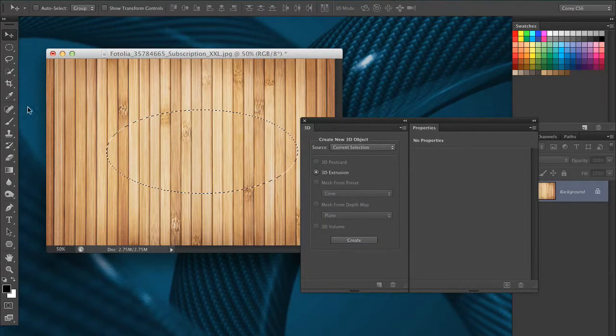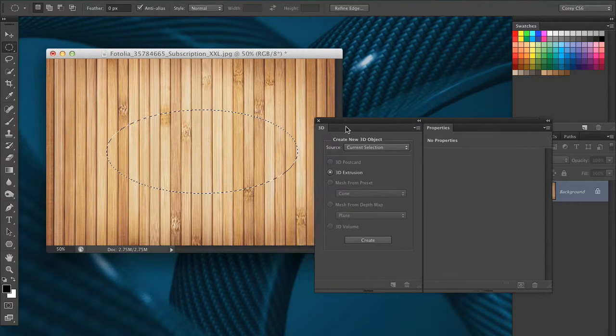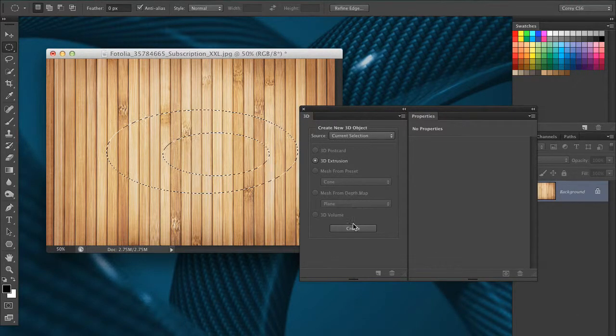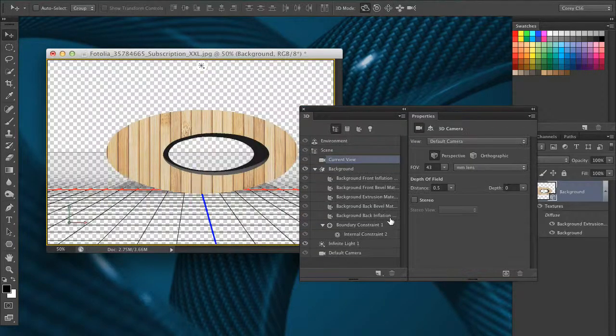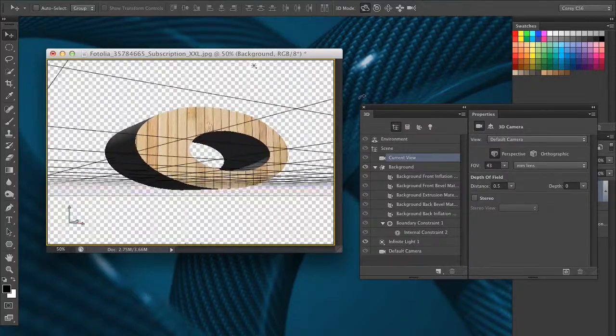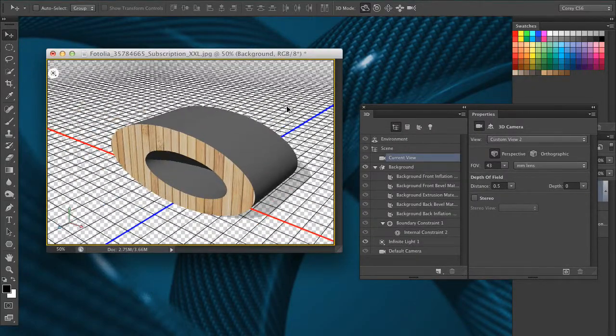Now going back a few steps, let's go back to where we had that active selection. If I were to knock out part of this selection, if I go in here and hold down my Option key on Mac, Alt on Windows, and just draw out a selection and basically subtract from that area, what's going to happen when I create my object? Well, beauty is, in CS6 it now will know that that selection is knocked out, and when you create the 3D object, it will punch that hole out in the object when it is in 3D. Pretty cool stuff.